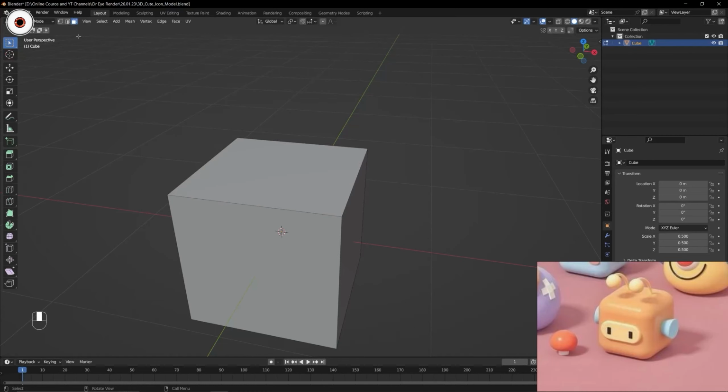You can switch between these three by pressing 1, 2 and 3. When you press 1, you switch to vertex mode, by pressing 2 you switch to edge mode, and you can see it here. By pressing 3 you switch to face mode. I hope it is clear. And go back to object mode.